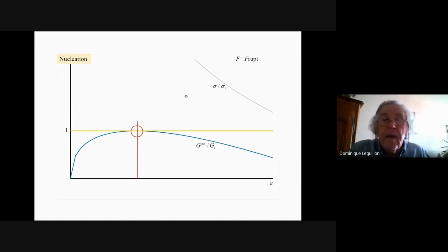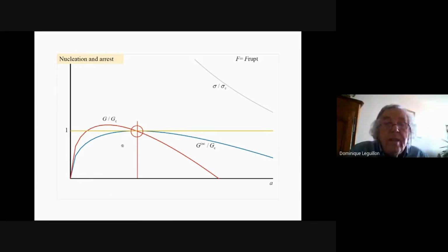Okay, so the coupled criterion can state that the crack jumps from here to here, for this value of the load. Then there is a crack now having this length. We can use Griffith. But what is interesting in this case, when the incremental energy has a horizontal tangent here, it's very easy to show that G is equal to G incremental at that point only. You see, at the other point, it's not true. But at that point, it is true.